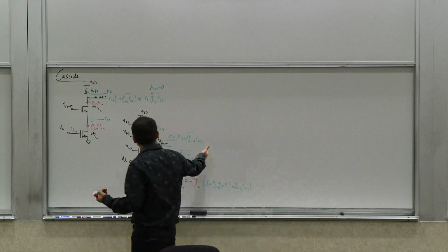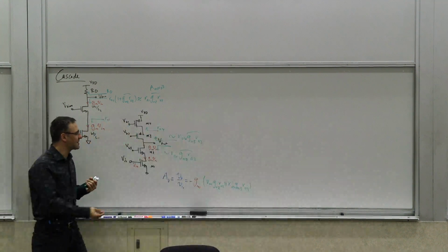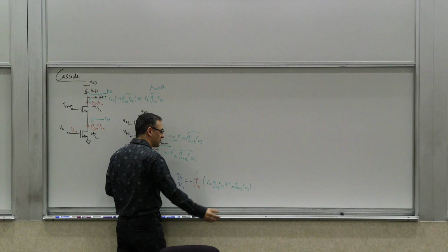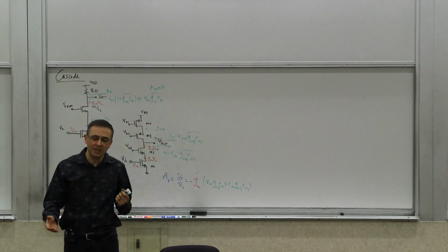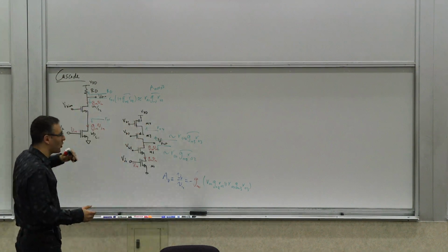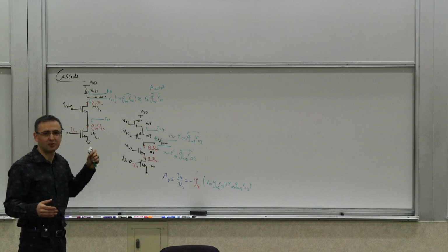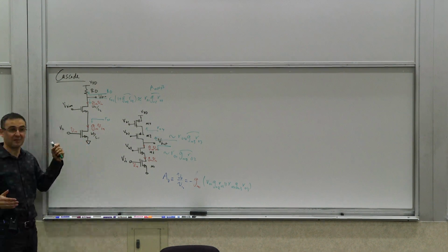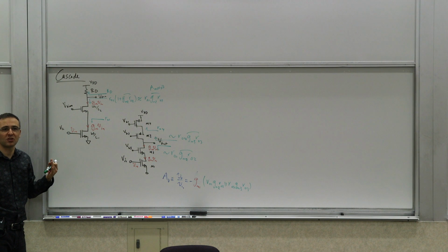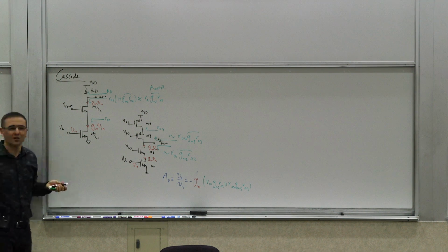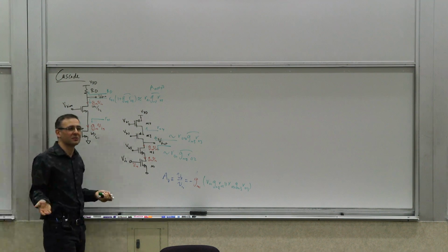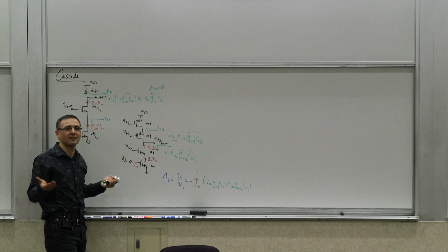So that's what you will get. Now, this thing can be large if the maximum intrinsic gain is large, so you basically increase it. And we saw that you can actually do a triple cascode, and you can get to ridiculously large numbers. You can even think about doing quad cascode. And at some point, we saw that if the numbers become too large, it means that essentially your model is starting to fail you, because there are other things you're not modeling.